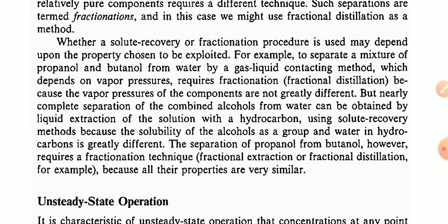But nearly complete separation of the combined alcohols from water can be obtained by liquid extraction of the solution with a hydrocarbon, using the solute recovery method, because the solubility of the alcohols as a group and of water in a hydrocarbon is greatly different. Some separations, such as propanol from butanol, however, require a fractionation technique, fractionation extraction or fractionation distillation, because all their properties are very similar.